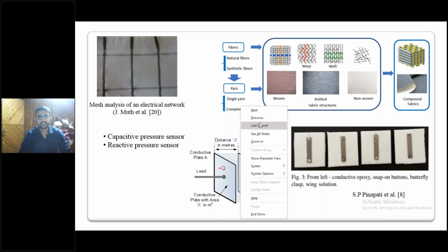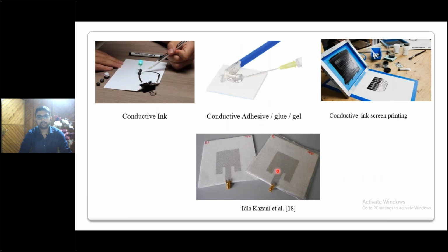And for this, once we make this electrical transducer, we have to feed it using a connector. Generally we use SMA connectors, because essentially, what is the objective? We want to feed this point using an alternating source, and this portion will emit radio waves. That is our target, and this portion has to be connected to a frequency or spectrum analyzer.